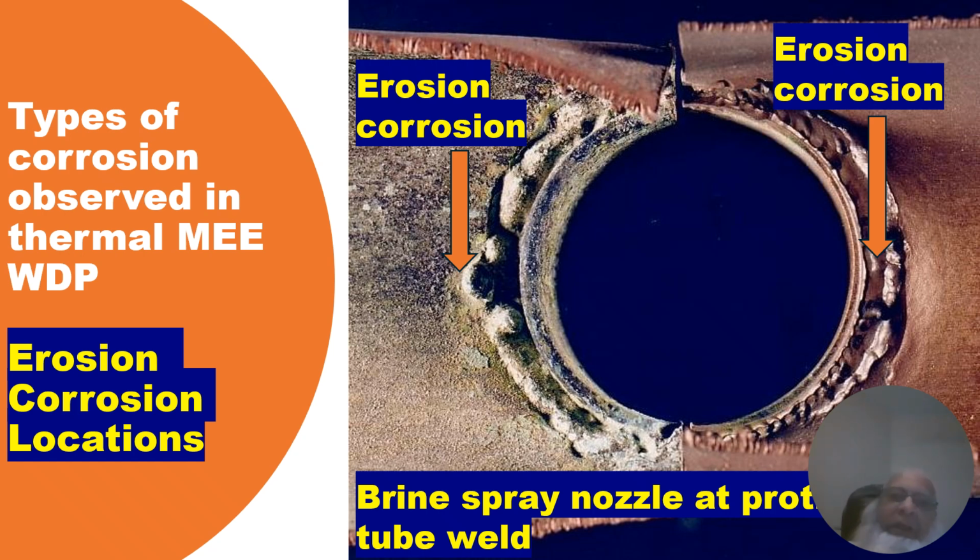It was actually a technical flaw, made on the understanding that if we protrude the spray tube into the header pipeline and do the welding, it will last longer. But on the contrary, the spray tube lasted only a very short period because of the erosion corrosion at the obstruction caused by the protruded end in the normal spray pipeline.